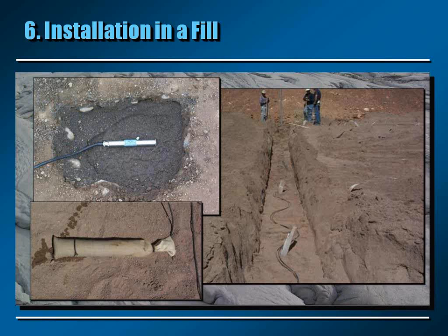The way the cable is installed in embankments or in dams is really important. It is important to put some slack in the cable, because the cable should not be damaged in the future by any movement during construction that can occur, you can have differential settlement. So this is why it is important to take some precautions when you are laying the cable in place.